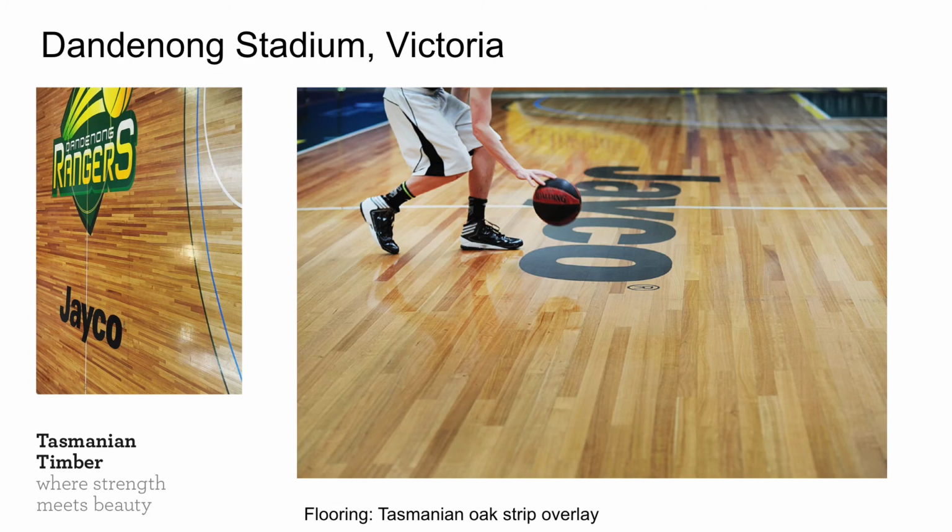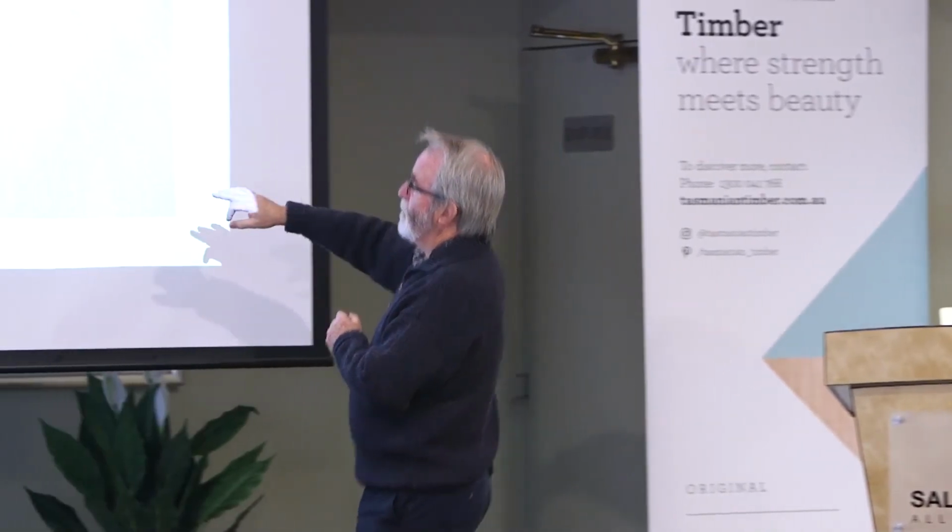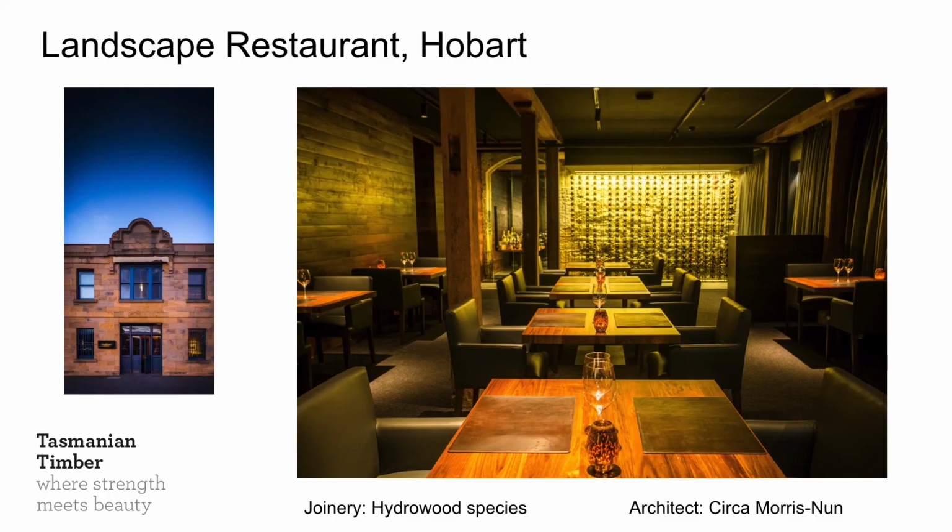Now at this floor, it looks like they're all glued together, but they're not. There'll be spaces in there. You'll see the boards are relatively small. They're not very wide, which with a basketball floor is good because you've got lots of little spaces. And you'll see that they're made up of random lengths. So looking at this from an observer's eye, this is actually an overlay floor that's been adhered to a substrate. The fact that it's glued will not stop it moving. It will still move. If it moves too much, it will pull itself off the glue if you get the moisture content situation wrong. But if you get it correct, then it'll be there 80, 90 years, and all you've got to do is recoat it every now and again.